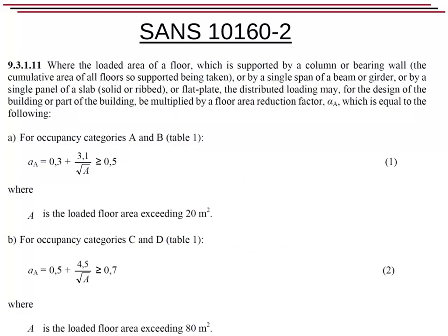But now, when you have a large area being supported, just imagine now, I was talking about a heavy safe on a beam or a floor, and if I was designing what's immediately below this heavy safe, I would make sure that the floor is sufficient. But that might be a 20 or 30 kPa load. But now it's not going to be on every square meter. So now I get down to, let's say, a 5 kPa, 5 kilonewtons per square meter load on the beam or the floor. But now let's say it's a 20-story building. What is the chance of every floor in the whole building being loaded all at once? And that is fairly low.